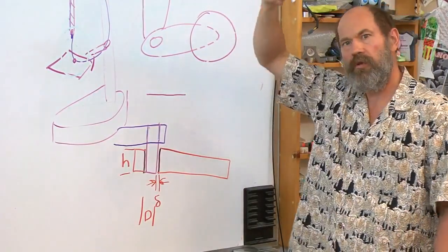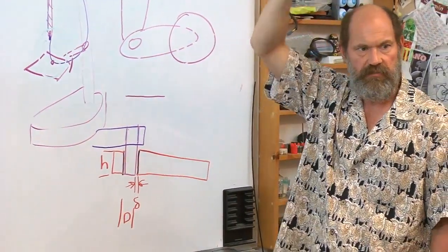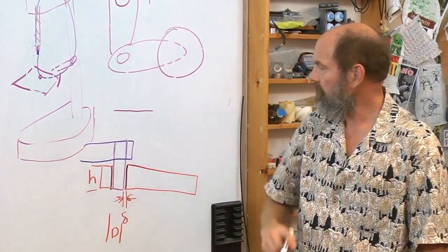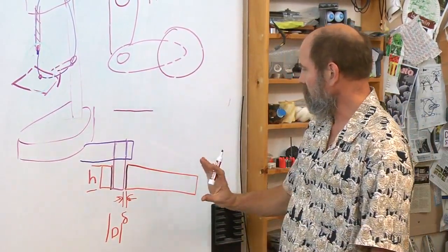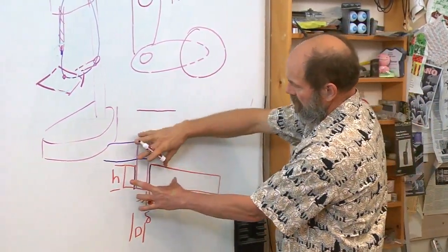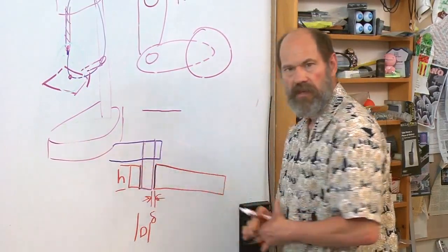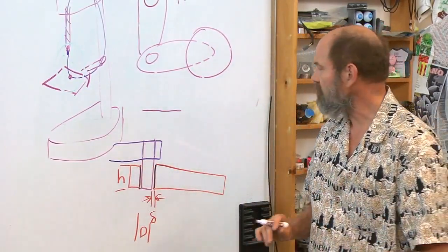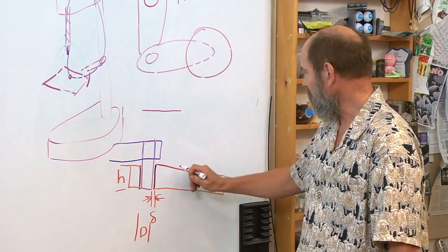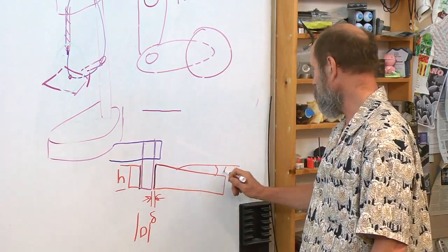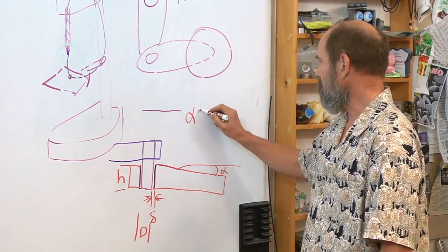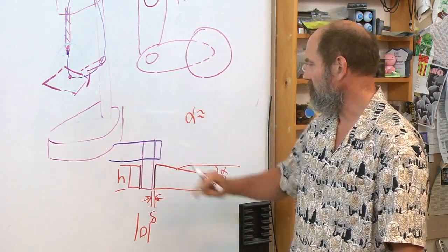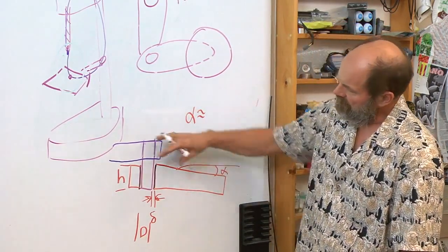When you go to drill a hole, you have a certain perpendicularity requirement. The customer expects things to be perpendicular. As I move this part, when I go to clamp it, is it always going to clamp in the same way or not? I don't know, but let's do a first order estimate of what this angle is and does that matter? The angle alpha, to the first order, we'll assume a small angle approximation here, is going to be what?